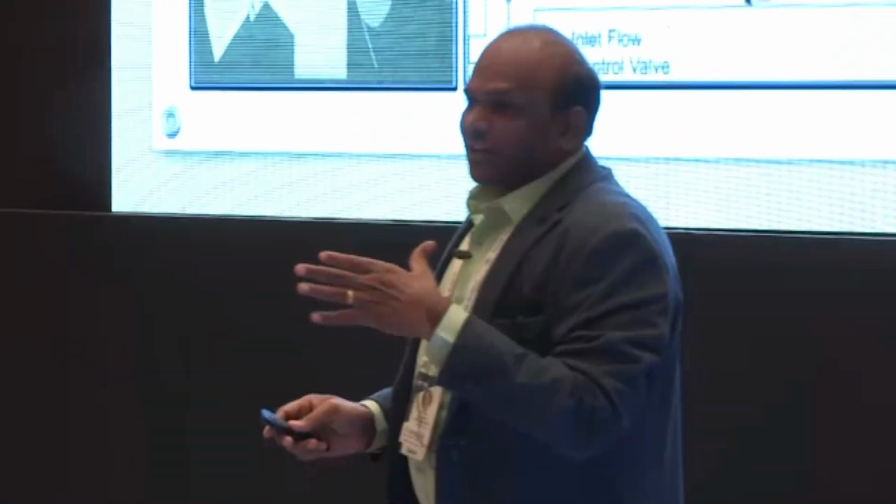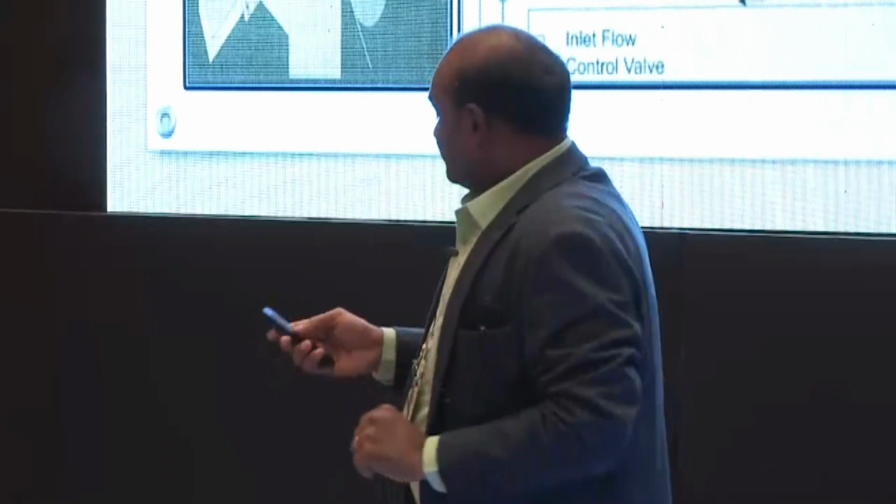This is a schematic of a common head box, and the first one is a side view of the head box and the second one is a front view of the head box. To maintain the pressure uniform across the machine, the pipeline is tapered here, across the width of the paper machine, okay? And the main component in the head box is the slice, similar to our tap. We open the tap and close the tap. Similarly, the slice is the key functional part in the head box.